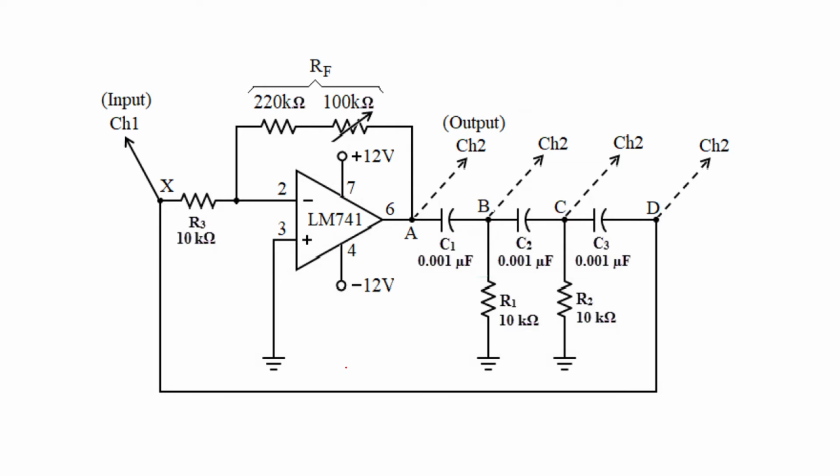So this is the circuit diagram that you have to construct. In the face-to-face lab, we use this to test and experiment which values will give a perfect sinusoidal. If the values are less than that, it will be damped and also clipped here. We don't want that. We want a full sinusoidal wave.